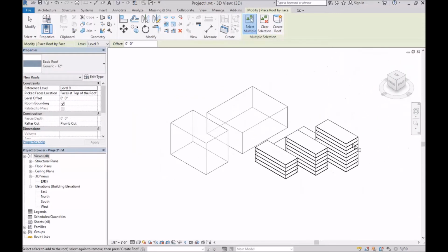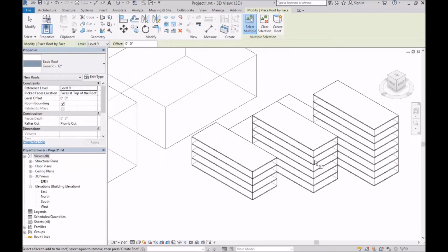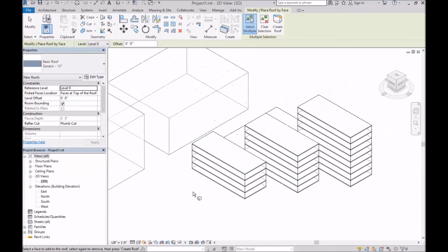Now that boundary issue also applies to floors where they encounter the edges of the envelope. So if you had balconies, for instance, or any type of floor element that was outside the building envelope, you would just want to make sure that that was split at the envelope and model it as two separate pieces. So the balcony piece would be separate from the interior floor plate. And the reason is that will allow you to then come back and tag that exterior element as shading down the road. And I'll show you how to do that in a little bit.